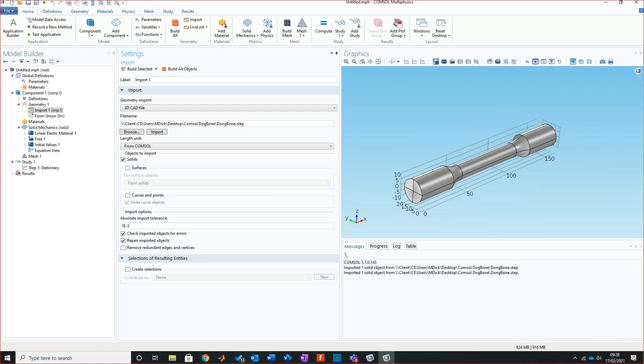So I drop surfaces completely. And then what actually happens is, because I've dropped surfaces, it refuses to try and bring any surfaces in and ensures what I'm getting is a solid. It's not something you've got to ignore. You can come back and check it again. You can do different things, make sure it's right.